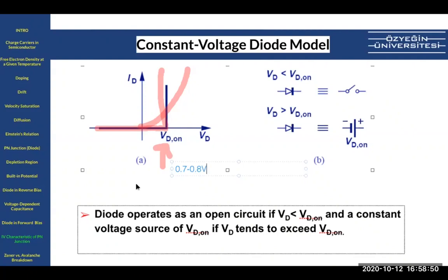Of course, for every semiconductor, this built-in potential voltage will be changing. And when we cross this built-in potential, the current will start to flow. For simple reasons, we just digitally show it like, after VD on, 0.7, the diode starts to conduct a current. This current doesn't mean it is infinite. It's a current that is dependent on the circuit.